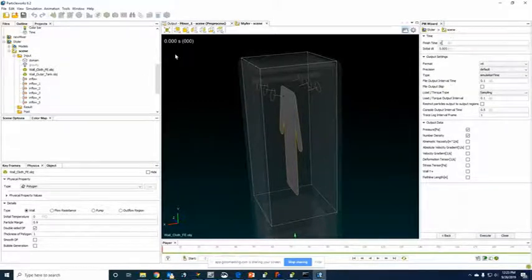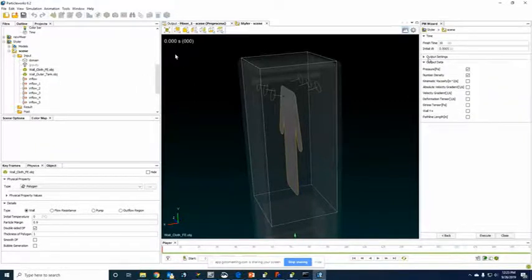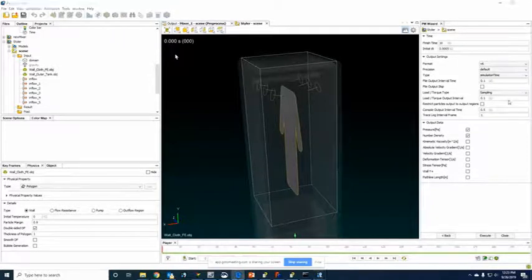And so now we're going to go ahead and set this initial DT. This is the time step. This can take a little bit of trial and error and some learning how to use Particleworks to set this appropriately, but we can offer training on that if you get to this step and you're trying to get a model working. We can offer some specific training on how to get these parameters set appropriately. But go ahead and just decrease that by a factor of 10 for now.